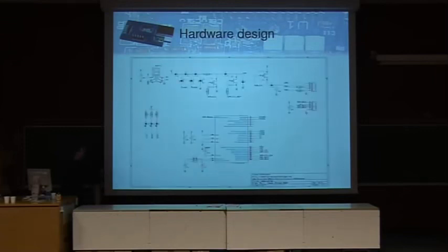For those who are interested in it, you probably can't read the text, but this is the whole schematic. You see the voltage pump here. This is the 5-volt, and there are some diodes, and those 2 pins are toggled in order to create a higher voltage, and some transistors to switch the programming voltage. These are the status LEDs, a USB connector, and the programming interface. Really, that's it.